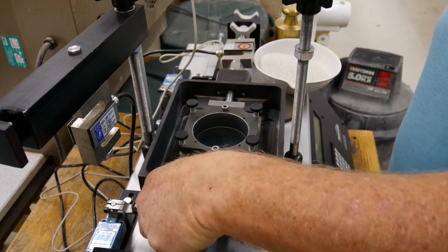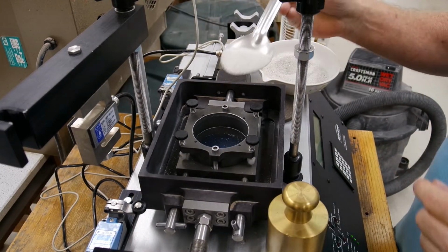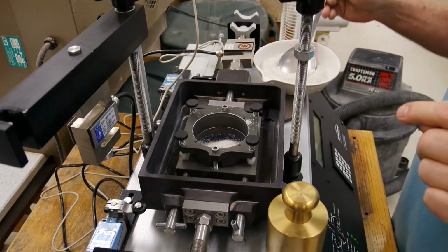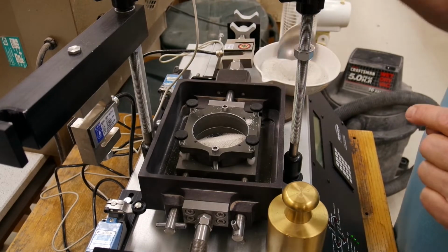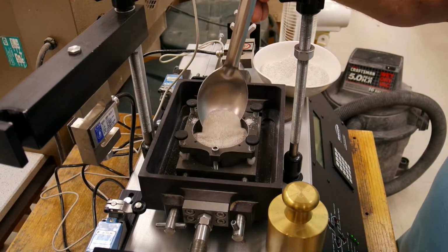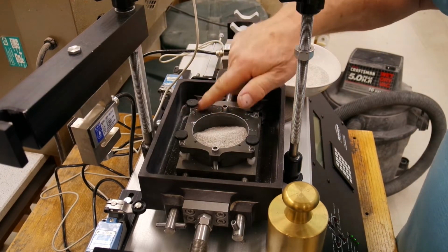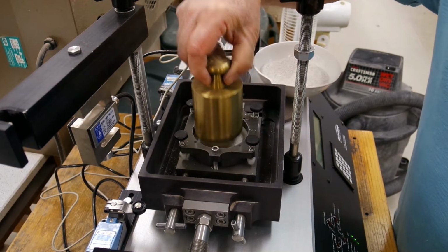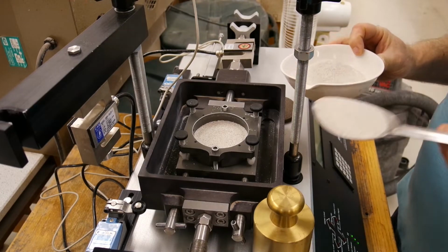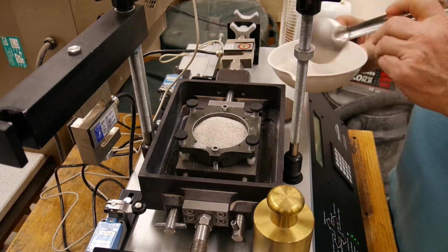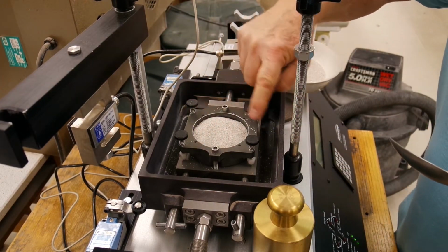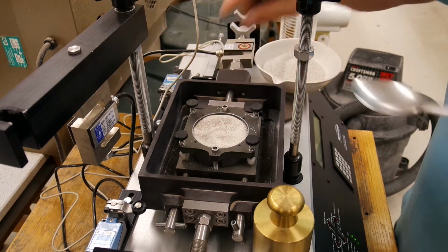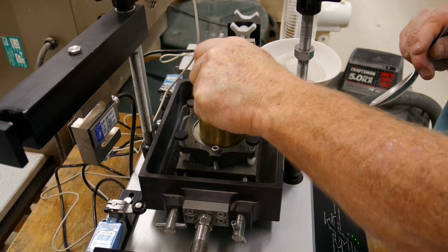We are ready to put in our sand. We will be using a silica sand for this test. We will put the sand in a bowl and get a weight, then pour it into our testing setup. Then we will use the hand compactor to compact the material so it is no longer loose. The density doesn't matter as long as we are consistent for all three samples.